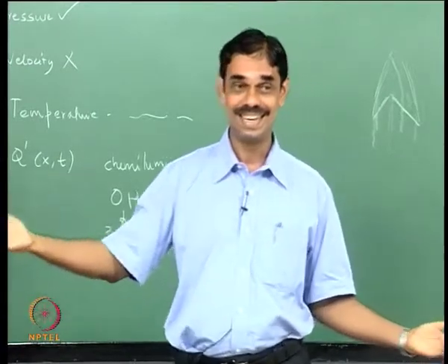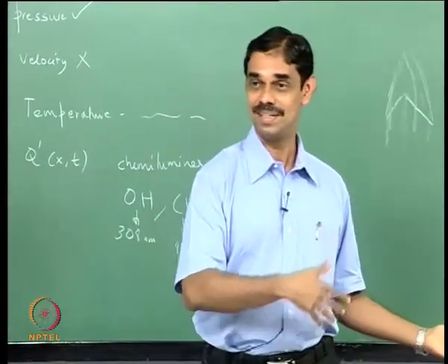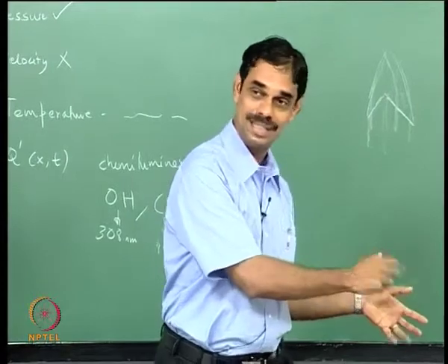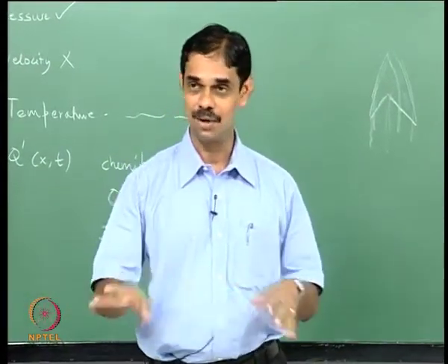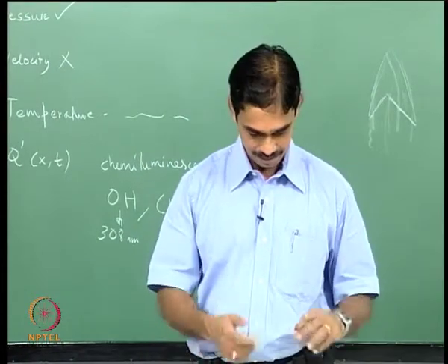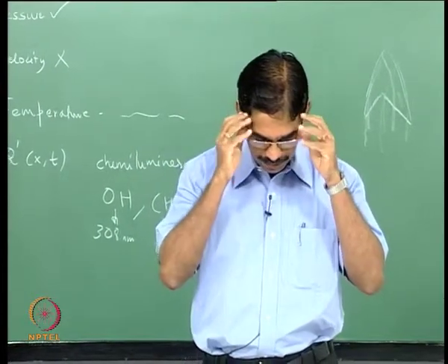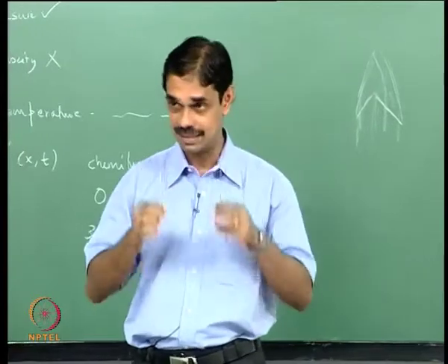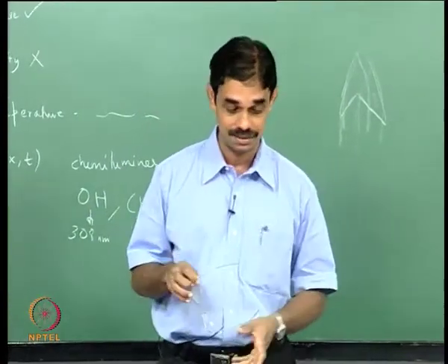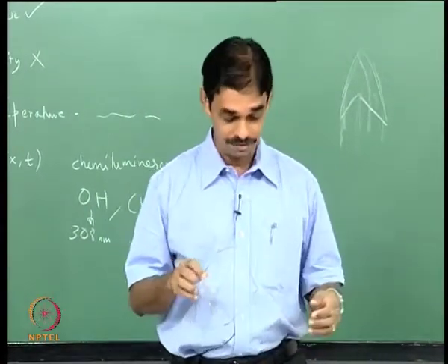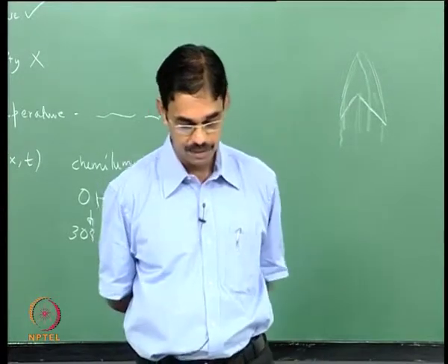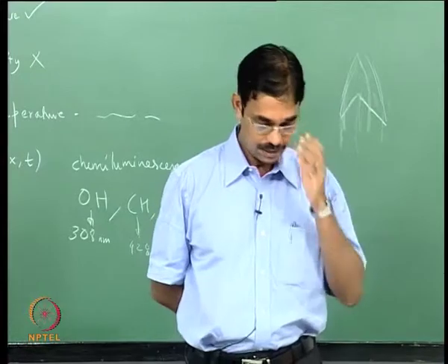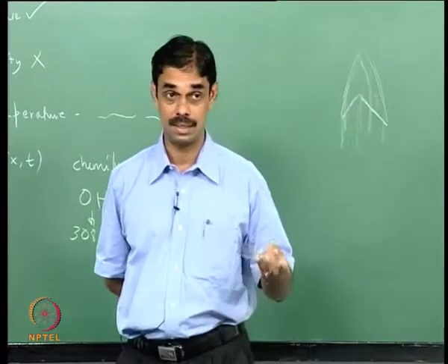As a combustor guy, he wants the combustor to burn, so you will see if this guy is having fun and he is making something. If it is going to work for me, I will buy it, otherwise leave it. So the economics will take care of itself. So we speak about actuators, which are a major irritant in this active control, because like I said, engineers don't believe that these things can work for so long. So satisfactory actuation of combustion systems presents a real challenge, because you have to operate these actuators under high temperature.